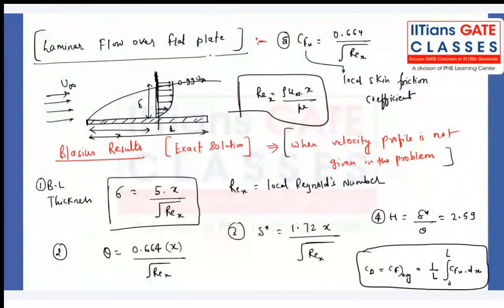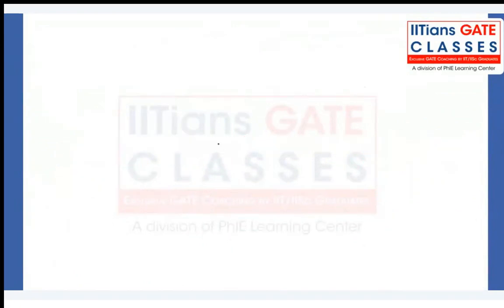Done? Note down CD value: 1 upon L, integral from 0 to L, Cfx into dx. That is 1.328 divided by the square root of REL. What is REL?